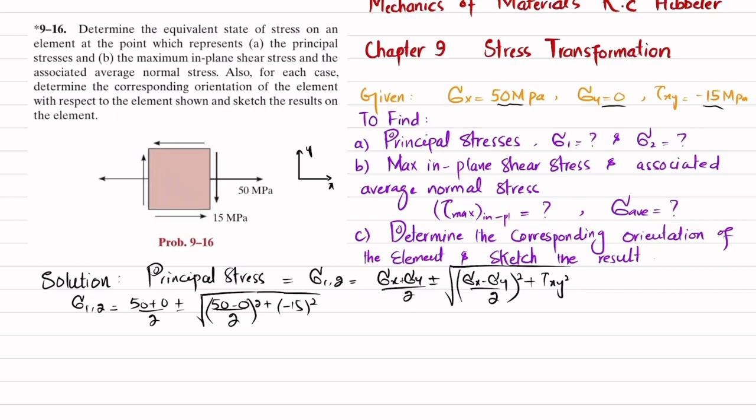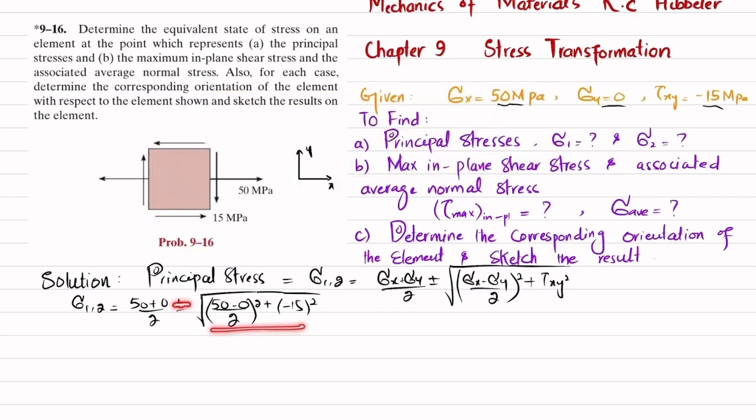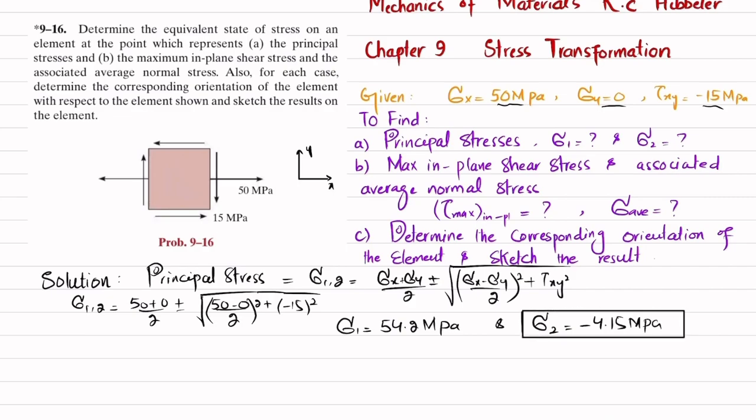So once when you take it first positive, it will be sigma 1, and sigma 2 will be 50 plus 0 divided by 2 minus the root term, and with this term it will give you sigma 2. So when you solve this, you will get sigma 1 will be equal to 54.2 megapascal, clear. And when you take it negative in between these two terms, so sigma 2 will be equal to minus 4.15 megapascal. So this sigma 1 and sigma 2 are principal stresses, which are the maximum stresses acting on the element.